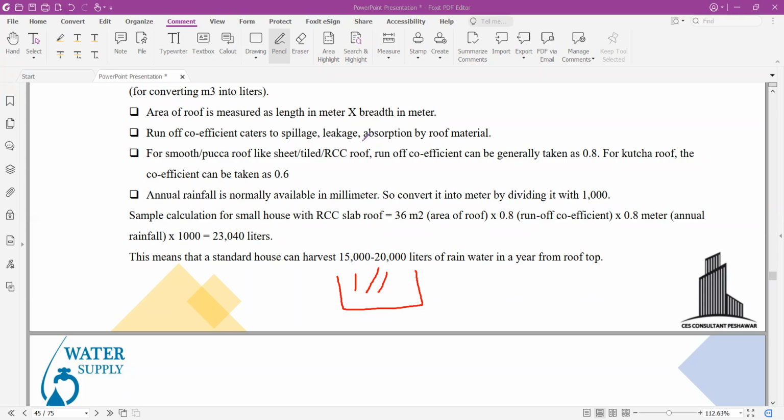Based on that capacity, we supply the water through the rising main to the storage tank, and we select, by the trial and error method, which diameter should be sufficient for a proper supply of water to that storage tank to minimize the losses through that pipe. So it depends on the condition. It's not a specific value that we will provide a 6-inch diameter or a 1 foot diameter.